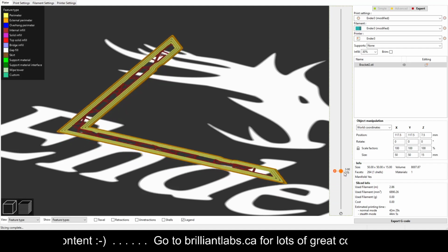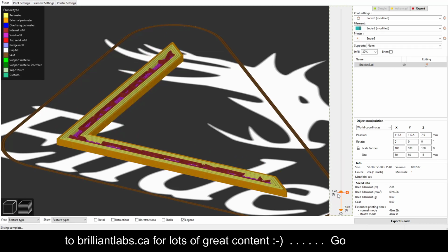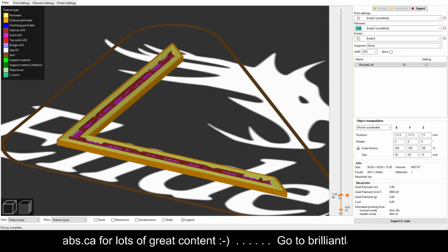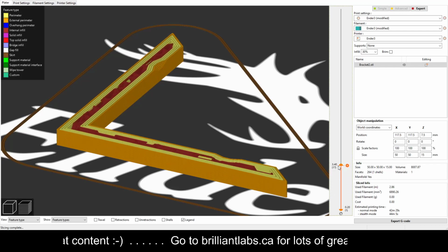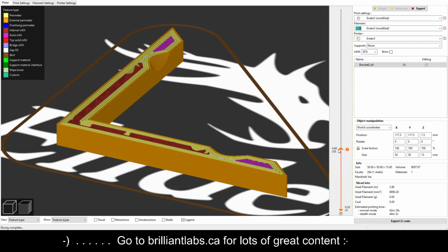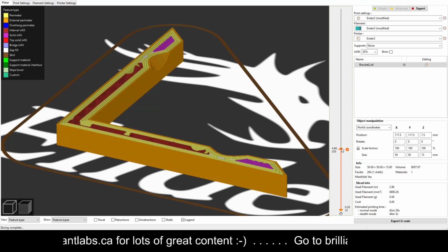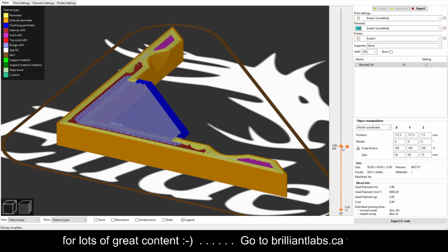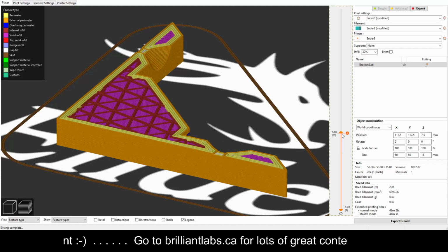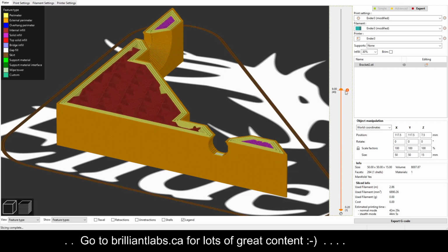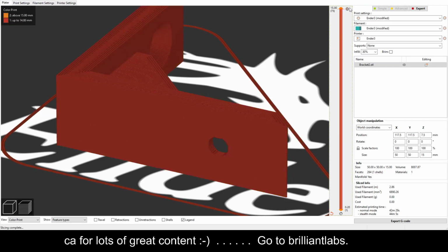And now you can see it printing. Let's pick the other one. You can see it printing infill after it finished printing the bottom layers. It's printing infill, the cubic version that we chose. Notice it printed that out, looks like out in midair, but it will actually work. Very, very close to not working, but it does. And it will go all the way to the top until it closes in our top layers.